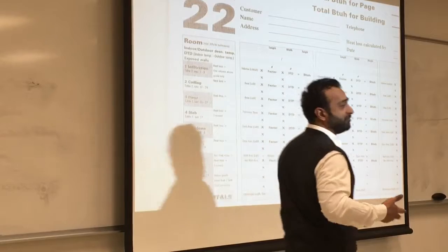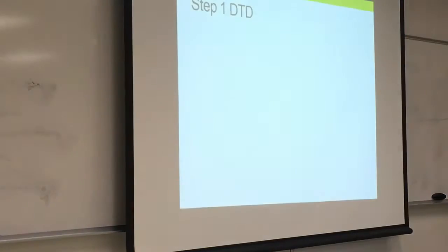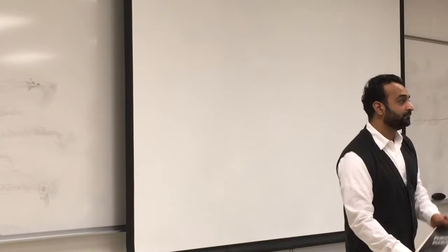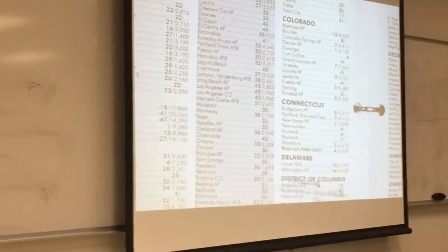And it's going to be the same for every room. So you go off the coldest day of the year, right? Where do you find that from? That book. And you said Springfield was 0? Yeah. It's the coldest temperature that the house will get to in the year, and that's over the last 10 years. Whatever temperature you want inside, you subtract that from the outside.